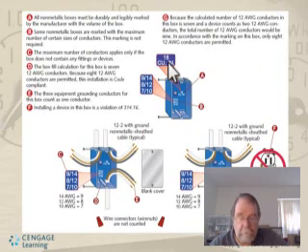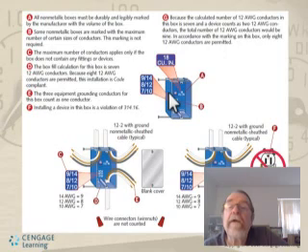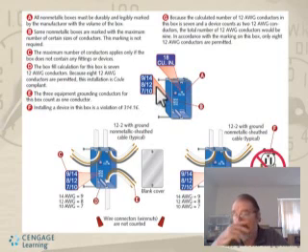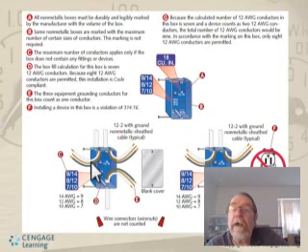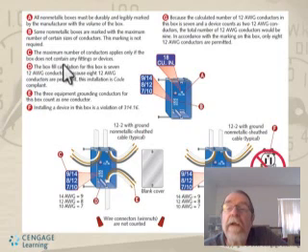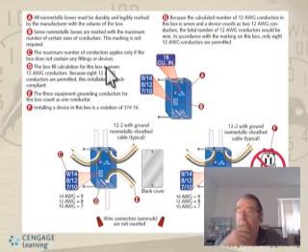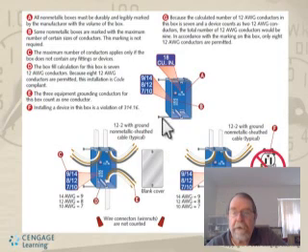Now on this page in your book, it shows the box, it shows the cubic inches, and the number of wires that you can have. Sometimes they'll put it on the box. There's the conductor size, and there's the number of conductors allowed in that box. The minimum number of conductors applies only if the box does not contain any fittings or devices. So in other words, if you have cable clamps in there that clamp inside, then those count as one conductor, and you take off from the number that the manufacturer has in here if you put a clamp in there.